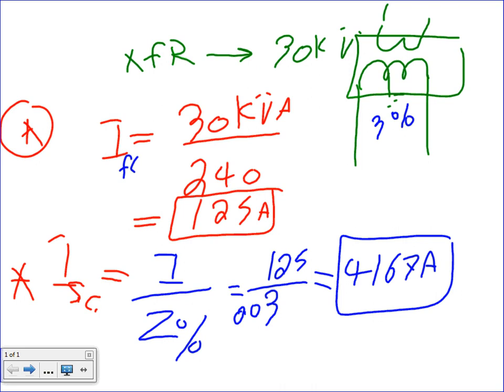And you ask, why doesn't this transformer burn? Because by design, by impedance, by cover, by insulation inside the transformer, it would not give you higher than this amps, and it's rated for this amps. They rate the cover and the insulation inside the windings for this amount of short circuit amps and full load amps. This, guys, you can hold forever.